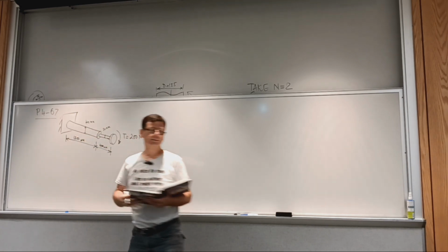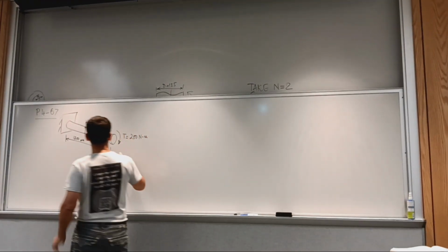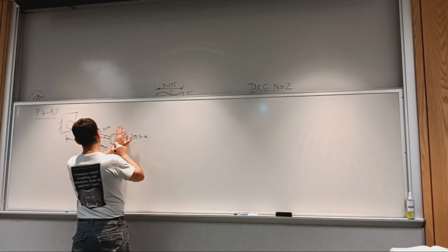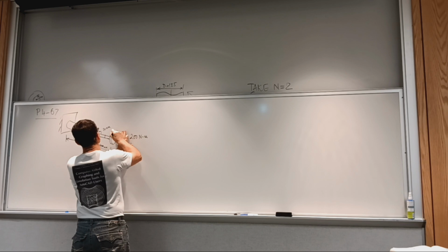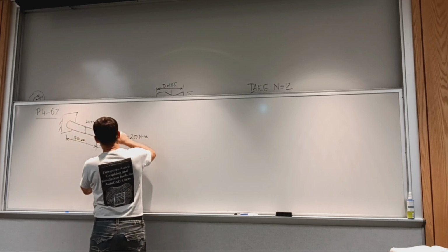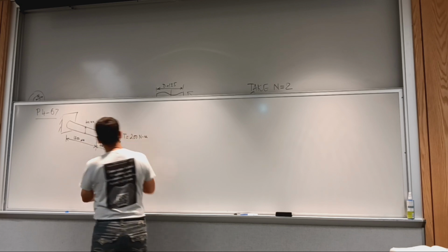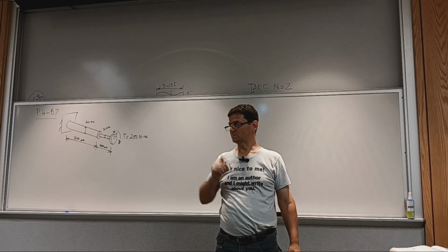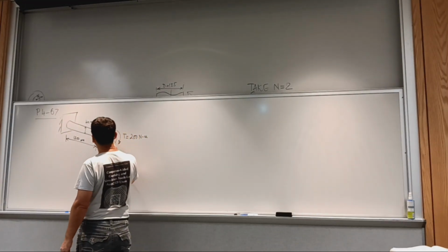But we have two sections. So how do you go about solving this problem? Again, you remove the load, or not apply the load, and you mark a line, and say you have a stationary reference, fixed together with this one. And then as you apply the torque, there will be a rotation in the direction of the torque by the amount theta in radians. Does it make sense?